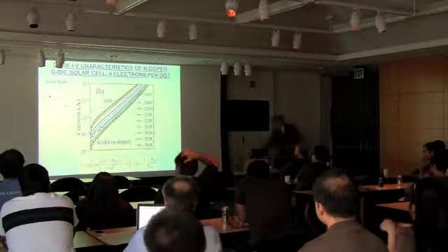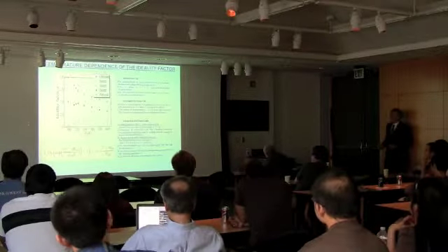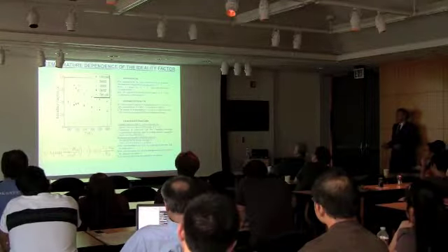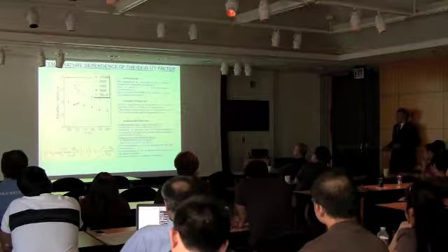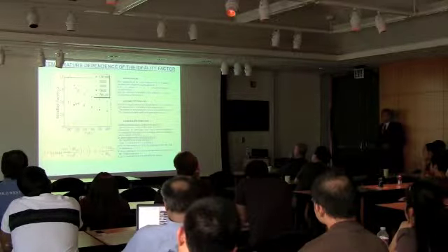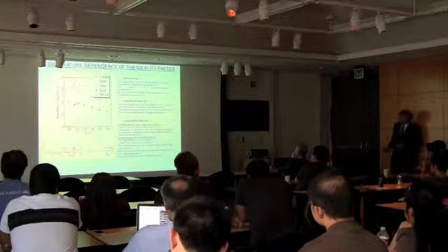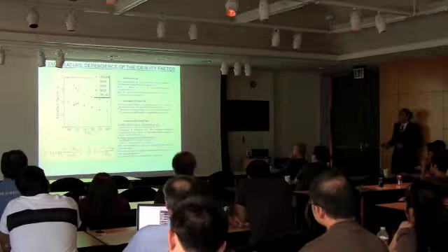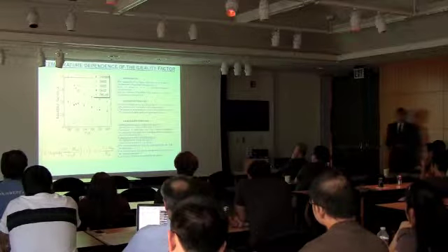So what is demonstrated here is, first, I show the ideality factor n. And it's again the same play: you have the reference cell, and the cell with the dots. So we have at room temperature 1.6, this ideality factor, which is a small number. Now, when we put in dots and put in undoped, you see that this factor increased by a factor of 2.